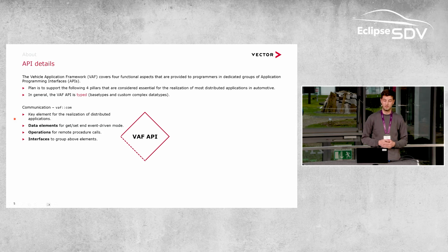Here we have done an abstraction, so we have data elements, abstracting in SOME/IP the events, in DDS the topics. So it's for data-centric communication, let's say, realized by getters and setters, and you have event-driven support. Then on top, operations for remote procedure calls.